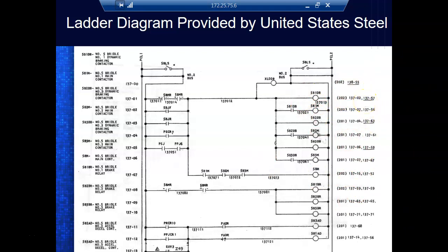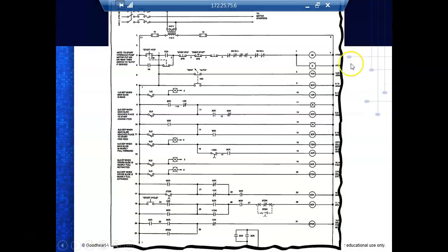A normally closed contact is the symbol that we showed y'all before. So it's got a line through it. So I'm going to come over here and see them on this print, but they cut them off. So that's line numbers right there. And notice line numbers are on the left of L1, and then contacts are given names.